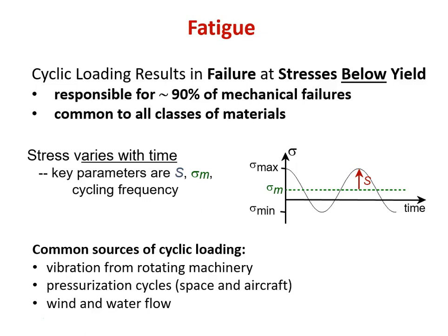This is in fact responsible for about 90% of mechanical failures. So if we don't have corrosion, we don't have a high temperature creep situation, or an environmental assisted cracking, chances are fatigue was the initial cause of the failure. The material will ultimately fail by spontaneous crack propagation once you grow that crack to beyond K1C, but it will probably be growing by fatigue.